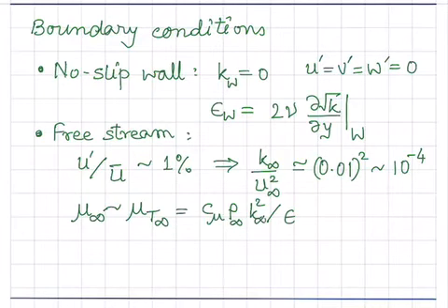Now everything is free stream value. So rho infinity, if it is given, rho is rho bar. K infinity, if we have computed using what we just showed earlier, we can, and mu infinity is a function of T infinity. This equation, with C mu given as 0.09, I think we specified as a model parameter, has only one unknown, which is epsilon infinity.